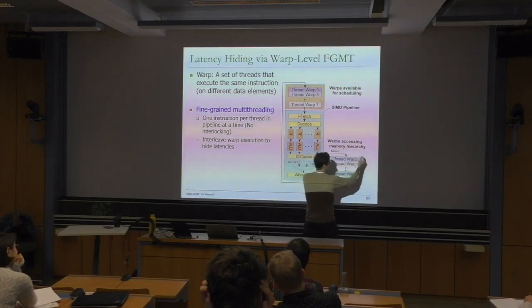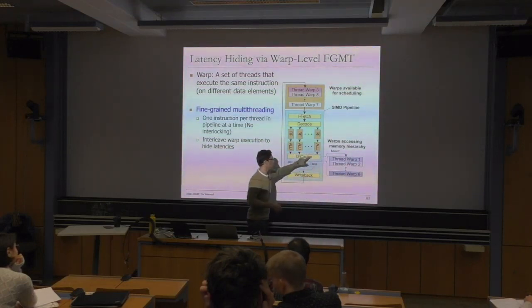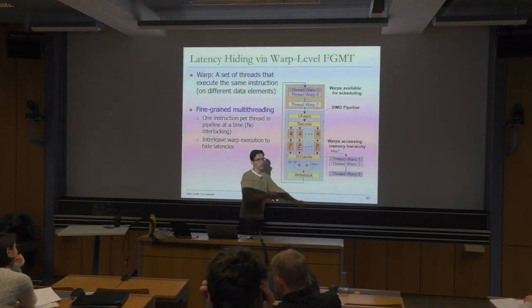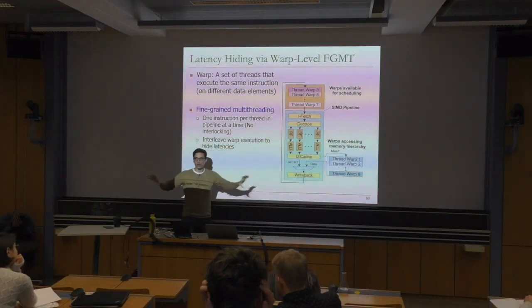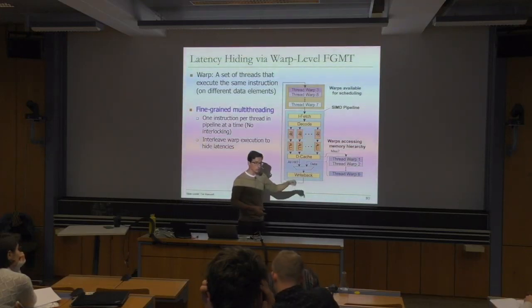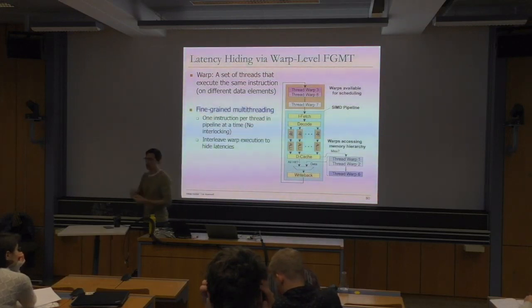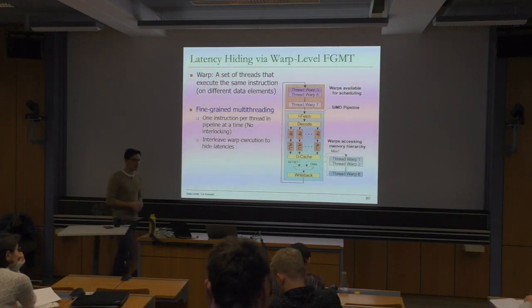You will typically have multiple of these. Each of them has an individual private D cache, but then they have a shared L2 cache. Now you go to L2 and you also miss, so you have to go to DRAM. And now you know how much time this takes: hundreds of cycles, maybe 500 cycles, which is a lot, right?